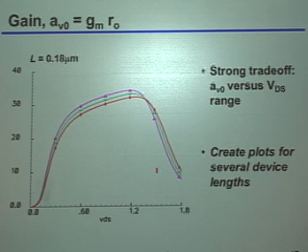Yeah, okay. You said the output swing, right? And that's exactly correct. So if somebody comes to me and says, my amplifier needs to have an output swing of somewhere between, let's say, 0.4 volts and, let's make it up, 1.3 volts, or whatever that number happens to be. Once you get that spec, you'd basically take this plot.